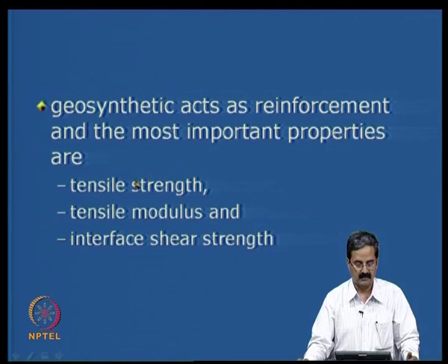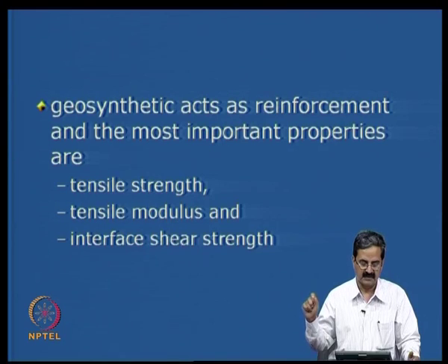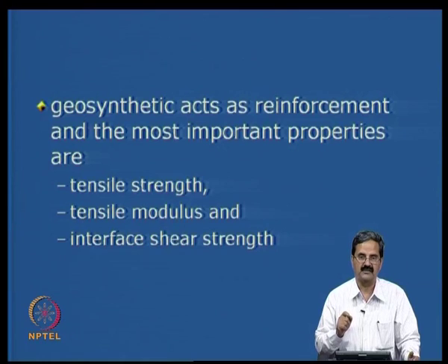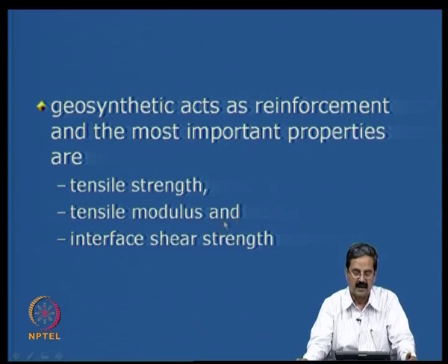Among the important properties, as I just mentioned, is tensile strength. For example, there is so much earth pressure developed, and with some spacing and length of the reinforcement, we get this tensile strength; we will see that. Tensile modulus is very important, because if there is a deformation, movement is very important, and reinforced soil walls also deform, and the modulus of deformation is very important. And the third one is interface shear strength, which is also very important. These three components are very important in the design.